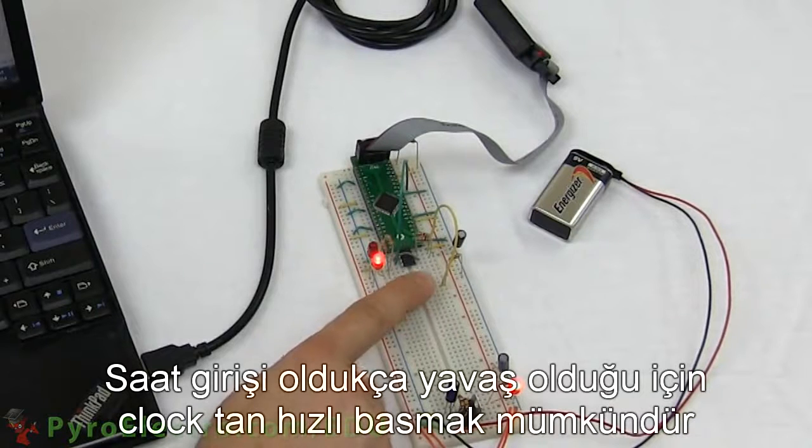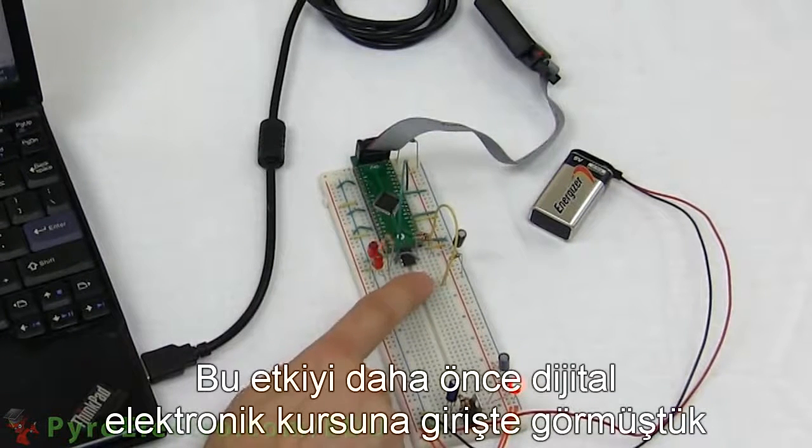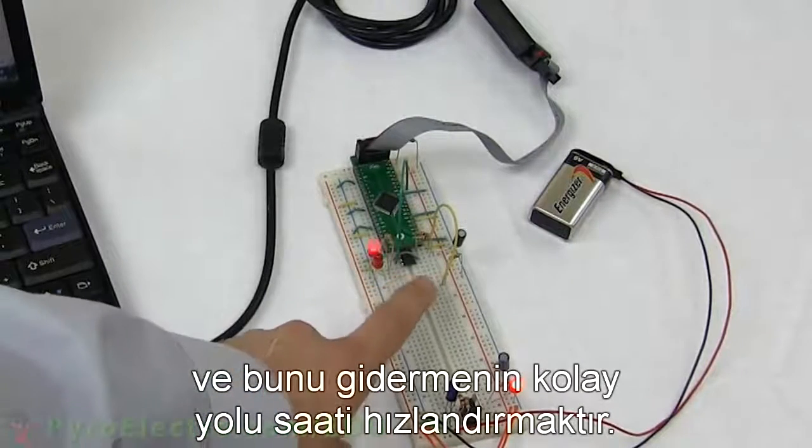Since our clock input is fairly slow, it is actually possible to press the input button faster than the clock, so that no output shows. We've seen this effect before in the Introduction to Digital Electronics course, and an easy way to make this go away is simply to speed up the clock.